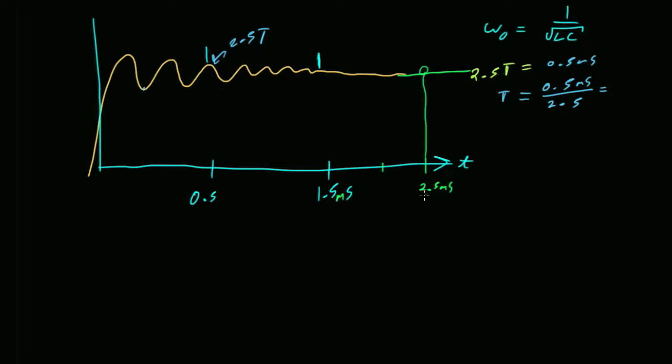So you could say 5 tau equals 2, 2.5, 3. That's your quick and dirty. That would give you a time constant. Once you know a time constant and you know your capacitance, you can solve for your resistor. Or if you want to get a bit more specific, you could look to see how long it takes to decay like 63%, maybe starting from initial value of 2. You could figure it out. That would be a little bit more accurate.